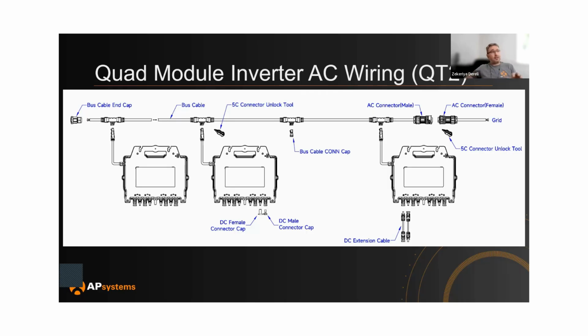Now, the distance between each microinverter is something that you would try to optimize, because you don't want them very far apart. Let's say they are within 3 meters of each other, then our options for the trunk cables are 2.4 meter, 4.6, and 9.5. I mean, 9.5, we don't really use. Most common are 2.4 and 4.6.